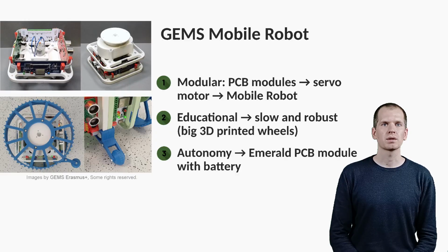They are connected in a circle with four flat cables that connect each board to the battery and the CAN bus. The modules are positioned between two 3D printed plates held together with four connectors. And one of the plates also holds a DC motor with a gear and encoder.